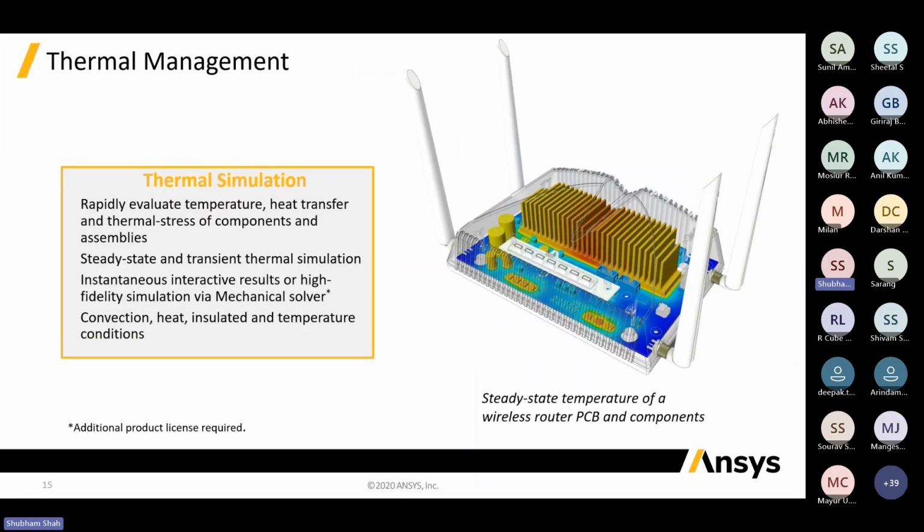Then there is another kind of simulation which can be done, that is the thermal management. So you can evaluate the temperature, heat transfer, and thermal stresses of the components and the assemblies. This can also be done using the steady state analysis, or you can go with the transient thermal simulation. You can link this with the high fidelity simulation for mechanical. You can club this with the Workbench physics, and then you can transfer this to the mechanical tool for the detailed or the in-depth simulation.